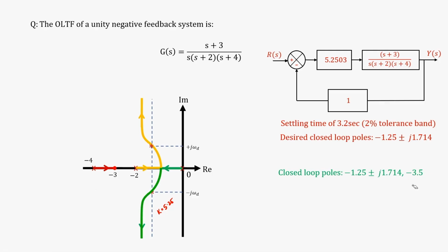One more thing is visible from this, you see, in this root locus you have no information about the zero location. Okay, from the root locus you can only tell where are the closed loop pole locations, right, because root locus is nothing but the drawing of the closed loop poles, right, as k is varied, correct. But in this case you see, there was a zero here, right, the zero was at -3, the zero information is now nowhere captured. What is the closed loop zero location?